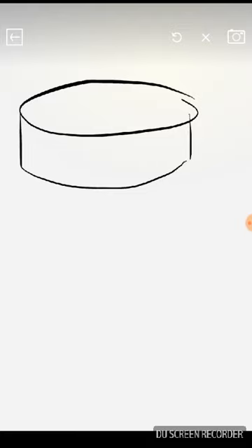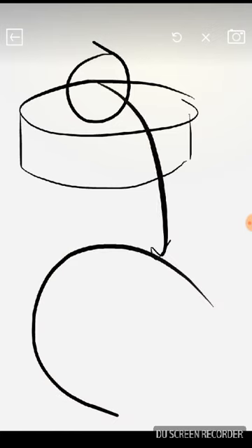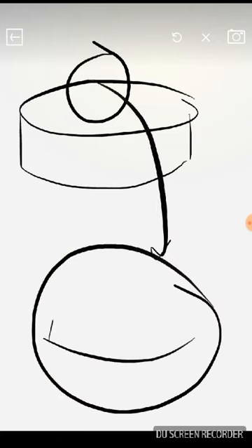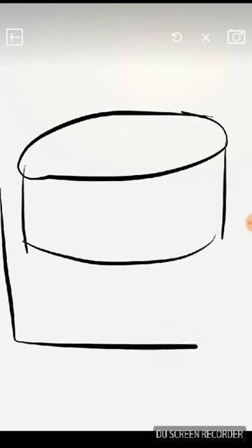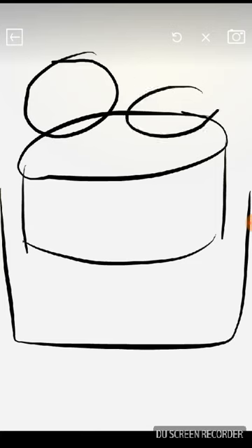While cutting, if you look macroscopically, it's okay. But if you look at it microscopically, then we can see that the edge gets a lot of unevenness. Thus a process of lapping is done, by which this unevenness is totally got rid of and the wafer becomes totally even. After this, the wafer is placed in a polishing tub, where some scrubbers come onto it and rotate at high speeds while polishing the silicon wafer.